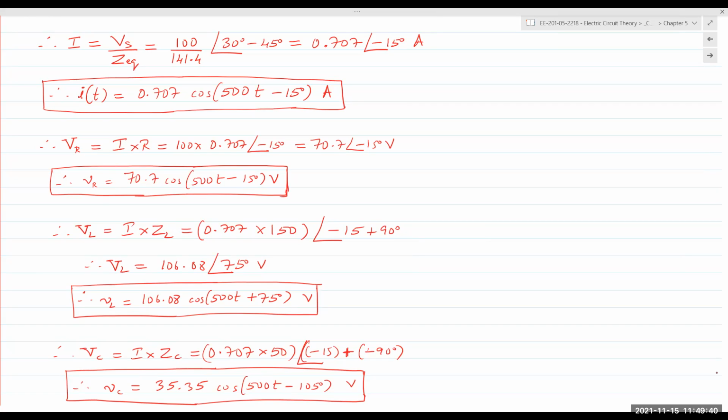So if you have a capacitor and an inductor in the same circuit, whether in series or parallel, in one half cycle, the energy flows out of the inductor and goes into the capacitor. In the other half cycle, it flows out of the capacitor and goes into the inductor. And it keeps going back and forth. Because of that, you have higher voltages and currents, at least in terms of magnitude, than the magnitude of the total source voltage.